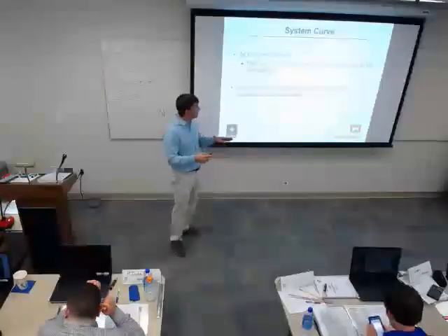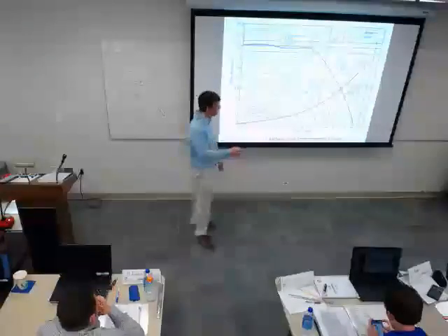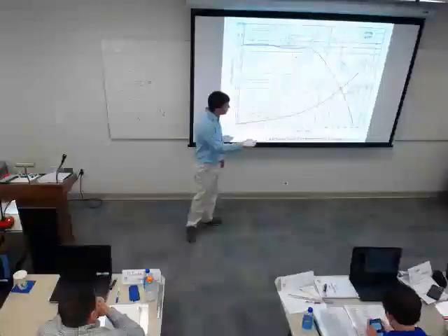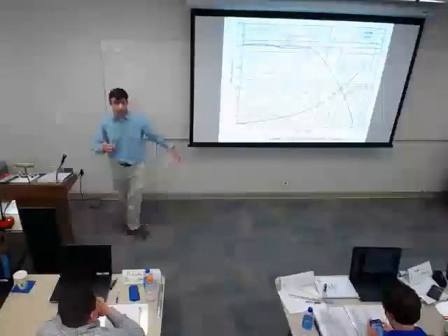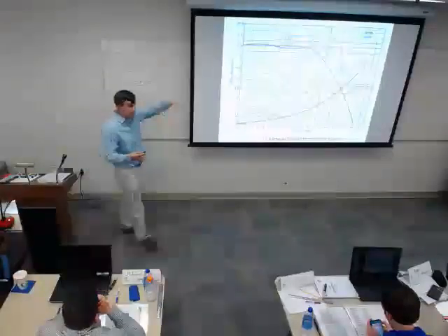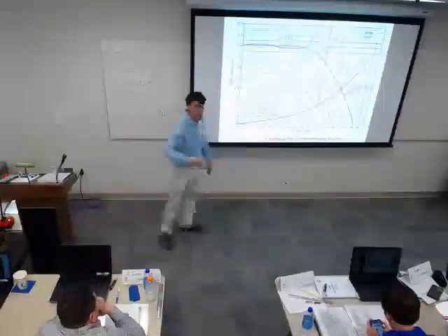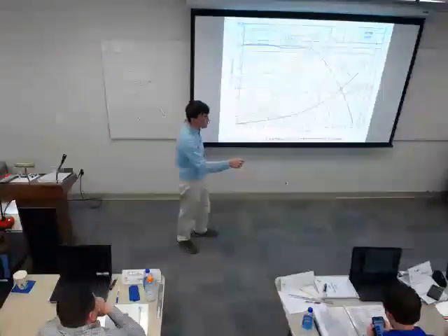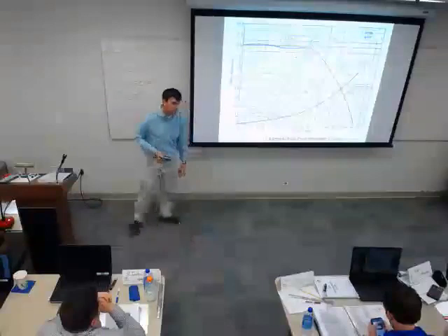The operating point also moves along the curve as the RPM changes. So what I can also do is change the RPM of my fan. Say I'm moving too much air, I can bring the speed down to 1200 RPM. I can do that with a sheave change, potentially, or if I have a VFD on it, I can just slow it down with the VFD. When I do that, I'm actually going to ride down the system curve. I didn't change the system at that point. I just changed the speed my fan was operating at. I have a new fan curve, and I'd be operating on this fan curve if I did that. Good?